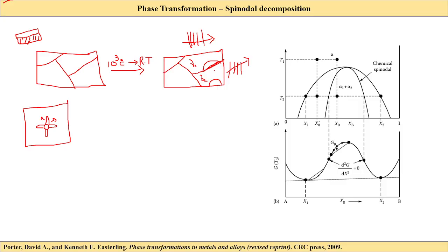To do that we need to strain the atoms of grain 1 or grain 2. Straining means we are increasing the total energy of the system. To minimize this strain, the system tries to grow a new phase here, and this phenomenon is called heterogeneous nucleation, right?